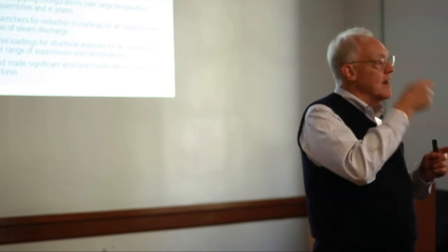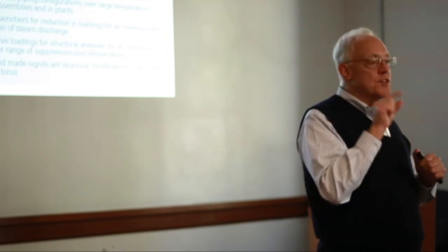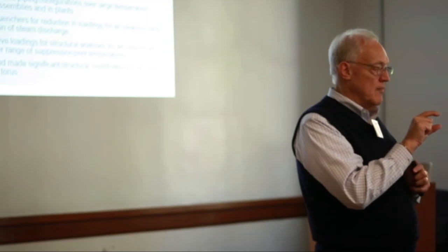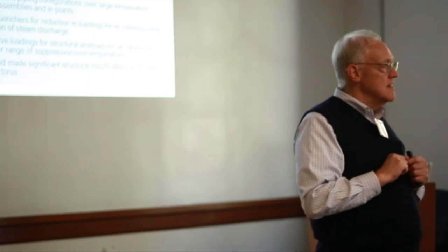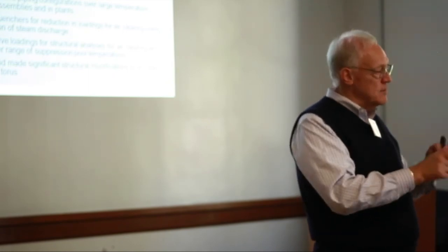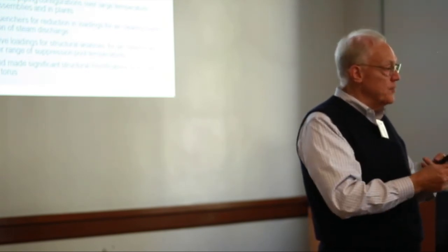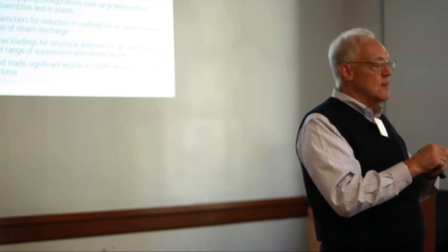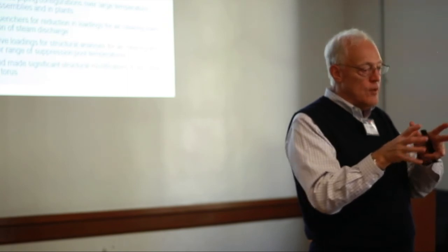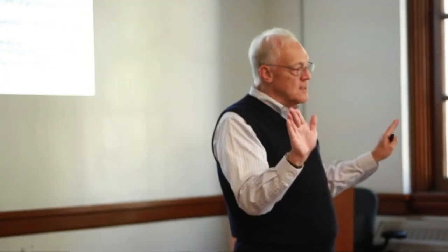So we took the operator out of the mode of trying to guess what the problem is, and put them in the mode of responding to what you see, and gave him some fundamental thought processes of what he has to control. I've got to control reactivity. I'm dealing with a water reactor now, so I've got to deal with reactivity. I've got to deal with inventory, water. I've got to remove decay heat. Very fundamental thought processes where he looks at the plant indications, what they're telling him, and how he assures that those fundamental requirements are fulfilled, and got him out of this discussion on events.